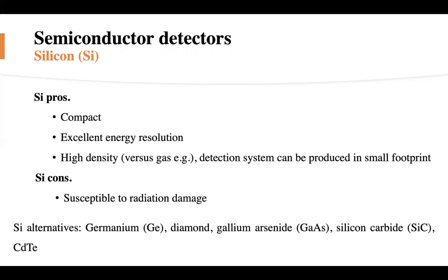We need a cooling system for that, because if you remember, or anyone who has studied semiconductors, there is something we call dark current. There is current, and we need to stop any current as long as the semiconductor is not exposed to radiation. So at normal temperature, the silicon can produce current. This will make it difficult to use as a detector, actually. So we need to cool it using a cooling system.